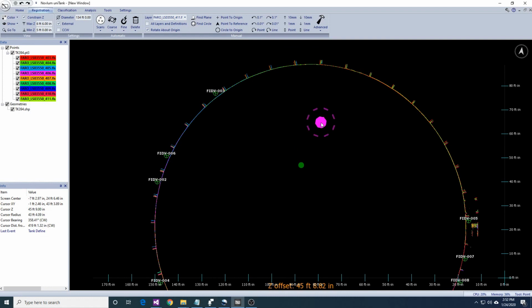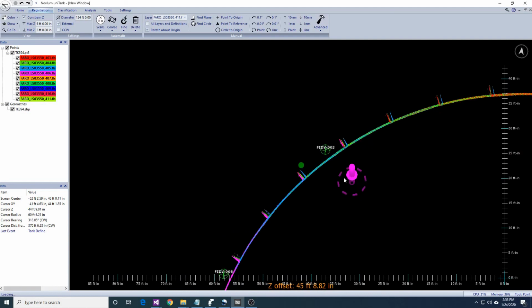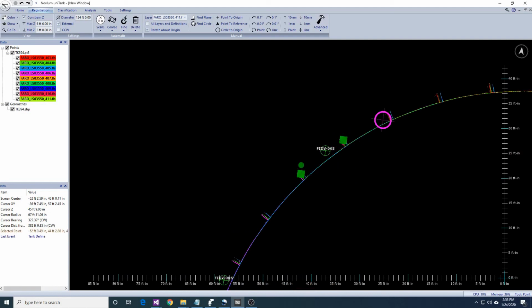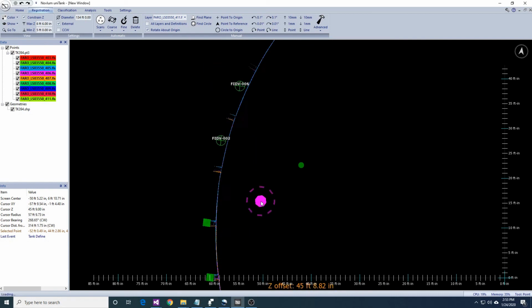Next, I will use the wind girder support flanges to add horizontal surface fiducials. Notice I am placing them closer to the tip of the flange. This ensures that the fiducial does not catch the shell data instead.